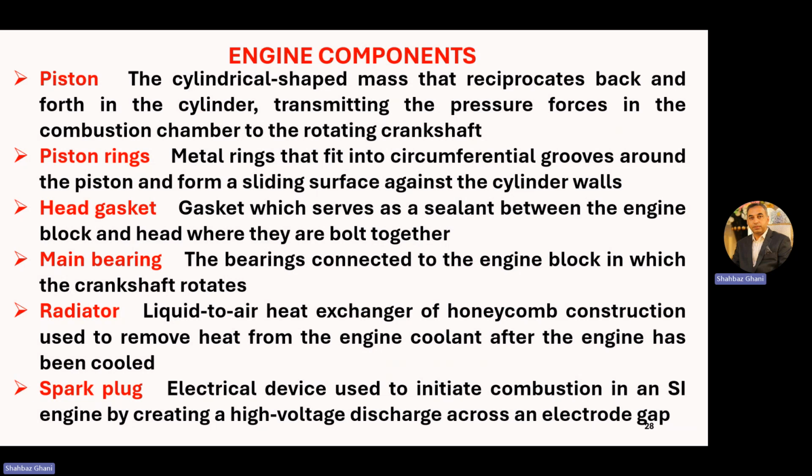First, on the top, we place the compression rings. Basically, that holds the compression in the combustion chamber, and the oil rings hold the oil in the lower portion, or scraper, which scrapes the oil from the walls of the cylinders.